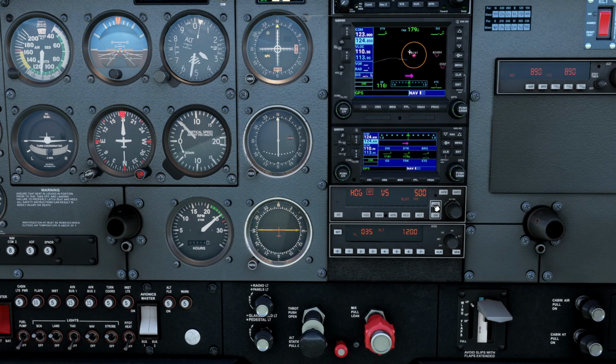I have to manually adjust the power, so I will put in full power for the climb. Aircraft initiates a 500 foot per minute descent, or excuse me, climb, and then it reverts back to the altitude hold display. If I want to adjust the vertical speed, I can do that by pressing the vertical trim buttons and changing that. It will momentarily go to a vertical speed display and then go back to the altitude pre-select display.